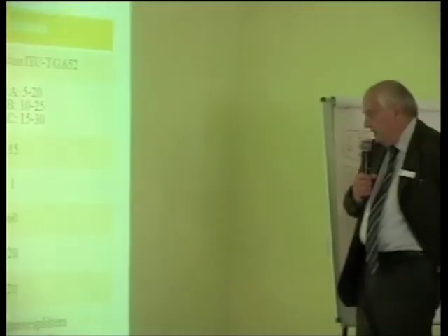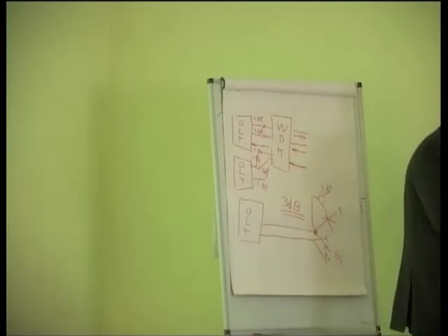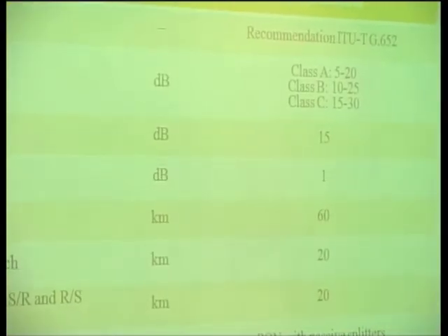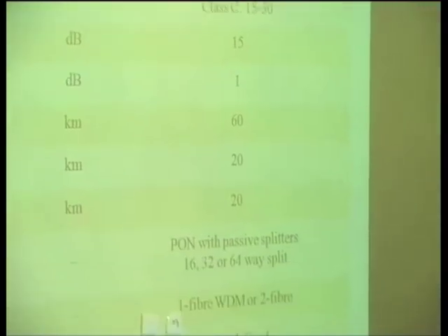And the bidirectional transmission, how can it be obtained? Well, in all the examples I have been showing to you, for sake of simplicity, I have always put just one fiber which is used in both directions with some sort of WDM multiplexing, which means two wavelengths in the third window in the downstream direction, one wavelength in the second window in the upstream direction. Of course, you should have two directions, but you can get them also by using two different fibers. You are not obliged to use the same fiber with two different wavelengths, but you can use two different fibers.